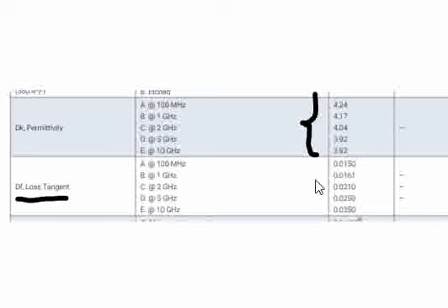So if we see here, for different frequencies the losses are different. That means in a PCB, based on the frequency, the losses are going to change. As the frequency increases, losses are going to increase. So if you see here, for 10 GHz signals, the loss tangent is around 0.025. This is in dB per inch, and so this basically is,